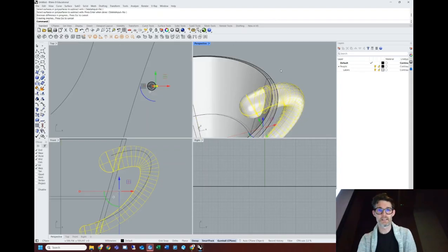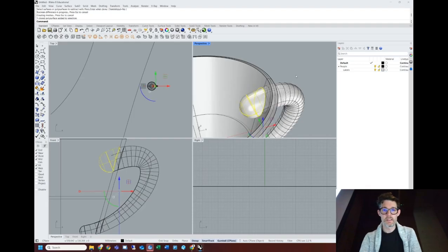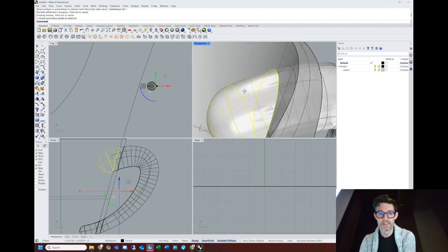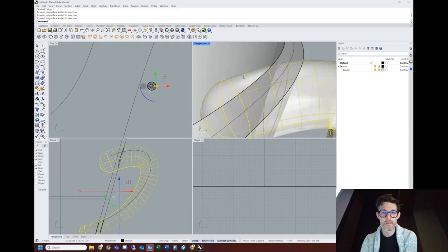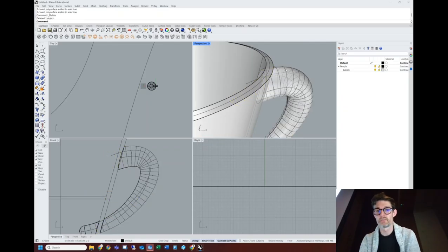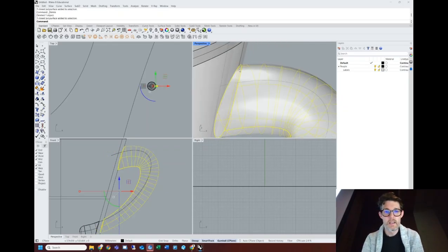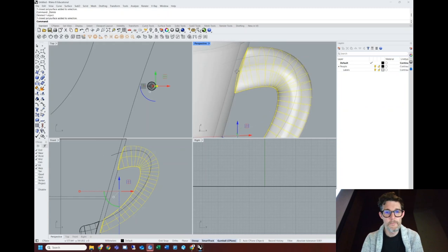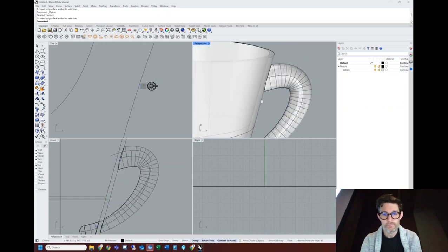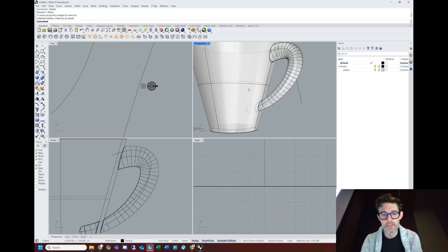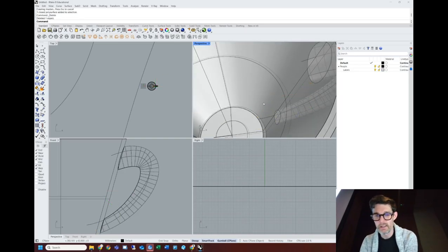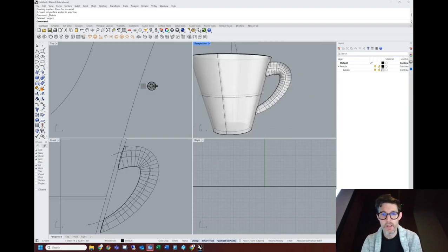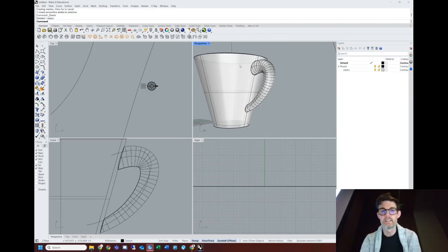Use this, press enter, and now here is one polysurface. It's sort of split it up. Here's another one. Oh, here's the original one. Actually, I don't need the original one. And then this one here, you can see that this line is now perfectly matched up with the surface of my quite complicated curve. And I can also get rid of this little guy here and press delete. And now I've got this really nice join between the revolved surface and my piped surface.